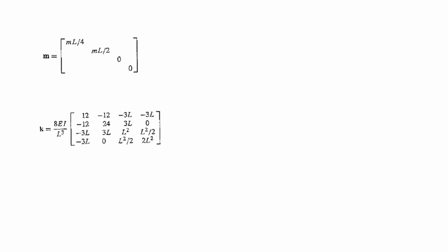Apart from this matrix, what is known to us is the load matrix, which is P1, P2. There is no load associated with P3 and P4 because they are the rotational degrees of freedom. No load is considered to be attached to them. Next, we have to determine the response, the static condensation response.